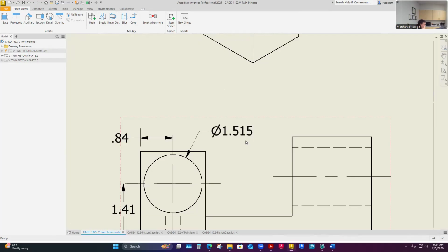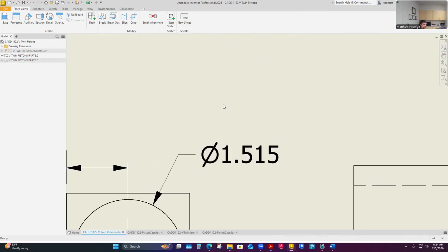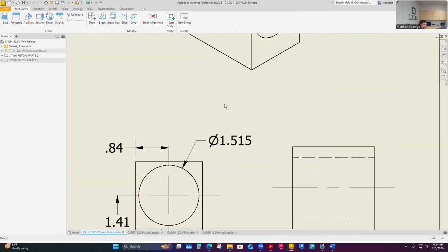That's good. In reality, I might want to add a couple thousandths and minus none as kind of a unilateral tolerance, or maybe it's bilateral only there, I guess. Only in one direction. Unilateral. Yeah, bias two. There we go. So a unilateral dimension.